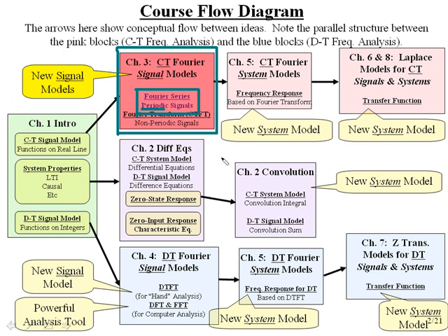And our goal, as we saw last time, was that by breaking a signal down into a sum of sinusoids, it provides us with a way of figuring out how each one of those sinusoids goes through a linear time invariant system. And since the system is linear, if we can figure out how each sinusoid in a summation at the input side goes through, then all we have to do is add up those individual responses, and it'll tell us what the output looks like. So this seems to be an alternative to convolution, and in fact it is.